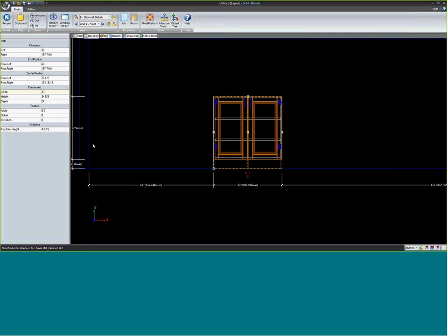it looks like nothing happened. The reason it didn't is because the default for a custom toe height comes in as exactly what our standard toe height is. But notice now I have this sidebar parameter. I didn't have that before. That double clicking enter caused this parameter to show up. So now I can type in whatever toe kick height I want, and the cabinet changes immediately.